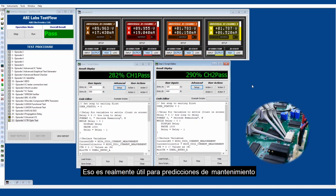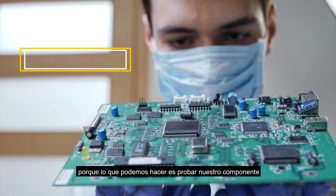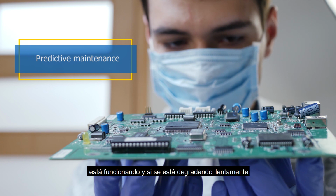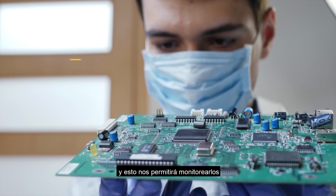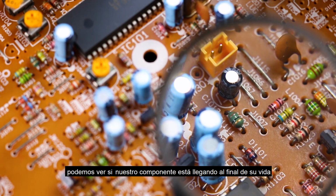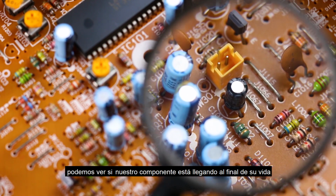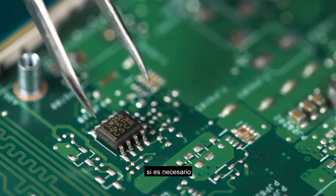So that's really useful for predictive maintenance, because what we can do is test our component and see how our component is operating and whether it is degrading slowly. And this will allow us, by monitoring the propagation delay as well as the CTR, to see whether our component is coming to the end of its life. And then obviously we can in time replace the component if necessary.